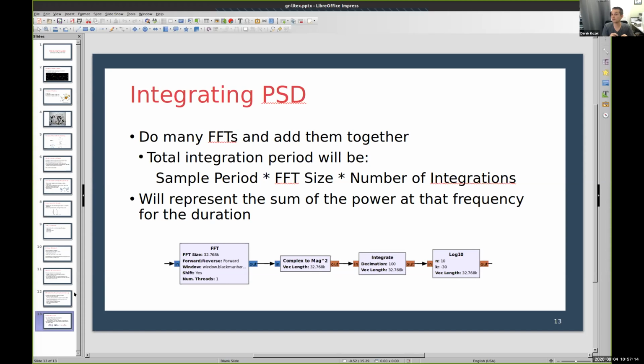There are many signals which you can pull out using an RTL that are stronger signals, but are still below the noise here on Earth. So Ellie, for instance, I know on a past project has used integration to pull out the hydrogen line observation data using an RTL and a relatively small antenna. So it is capable as a receiver.